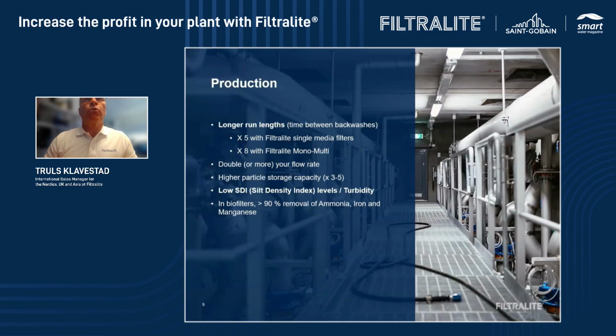So if you focus on the production, there's a study that has been done by Thames Water that shows that if you compare single media sand with single media Filtralite, you can run the filter 5 times longer. That means instead of backwashing the sand filter once a day, you can backwash the Filtralite filter every 5 days.